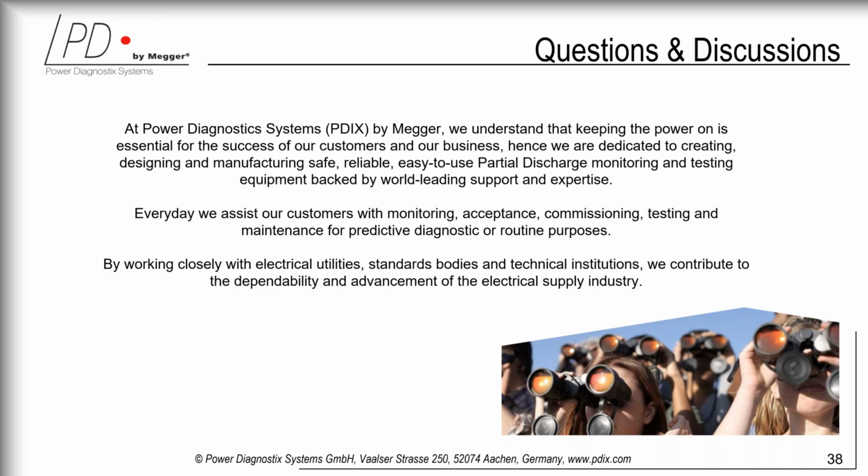All right, thank you. Mihai, did I understand that your line of products will detect PD prior to chemical analysis reflects internal issues? Yeah, so we understand that partial discharge within a transformer, those very initial sparks within the insulation, together with, of course, the behavior of the paper, are generating explosive gases.